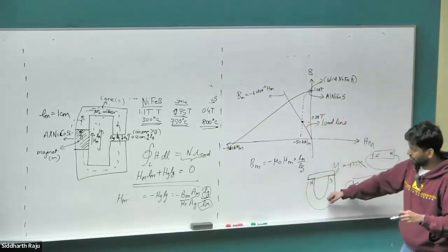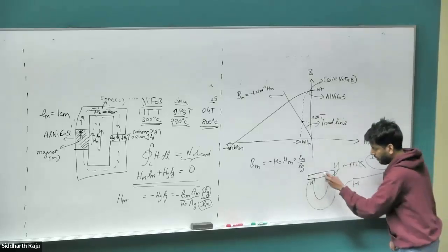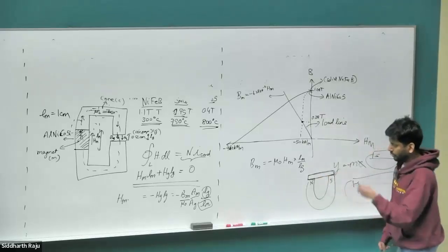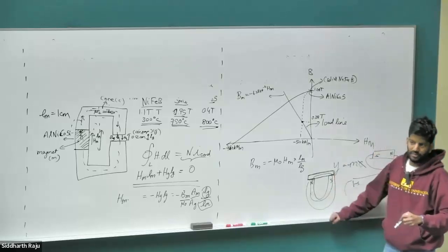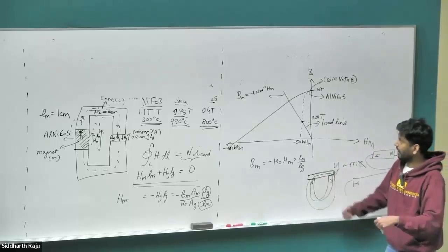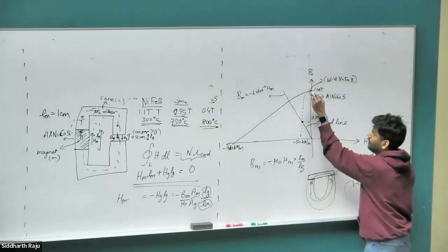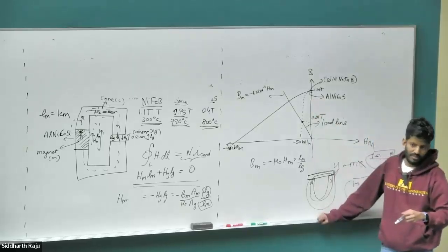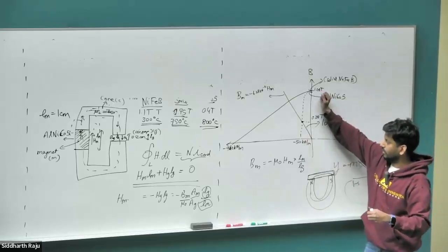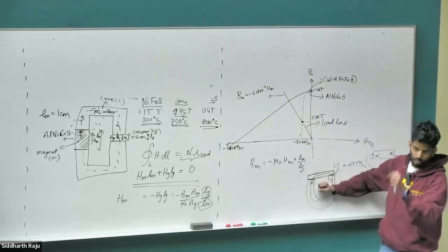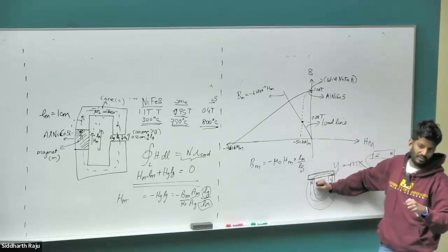And another thing is, whenever you store these magnets, you'll always put a plate on top of them, so that there is no air gap through which the field completes, but it completes through the iron itself. So if you close this kind of path, then the B field goes back to its retentivity value, 1.25 Tesla. So there is a significant amount of external field that needs to be applied to demagnetize this closed magnet. If you leave it open, it can get quickly demagnetized.